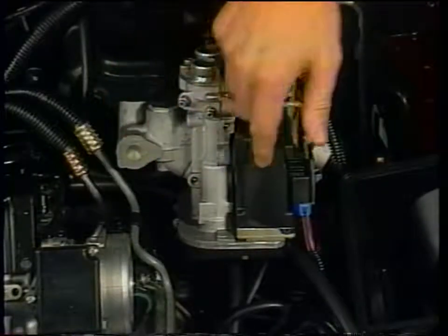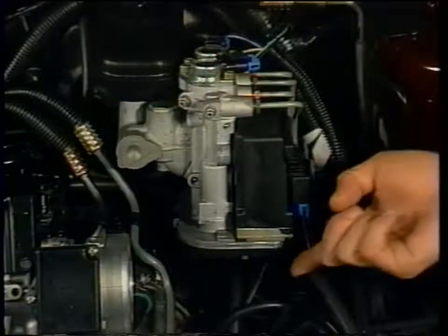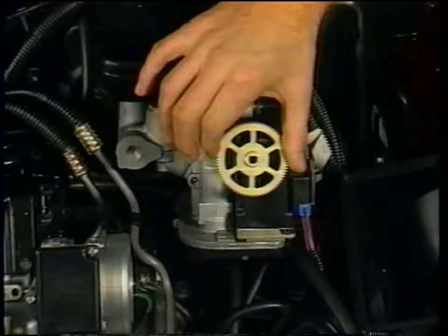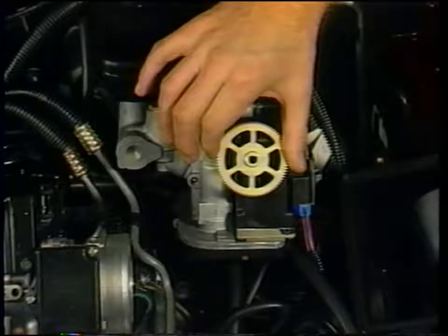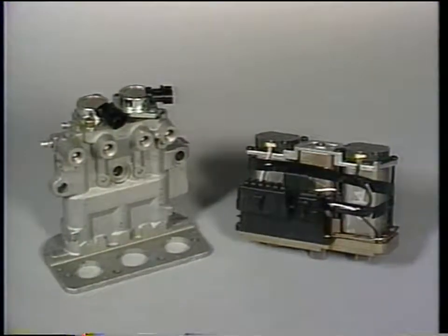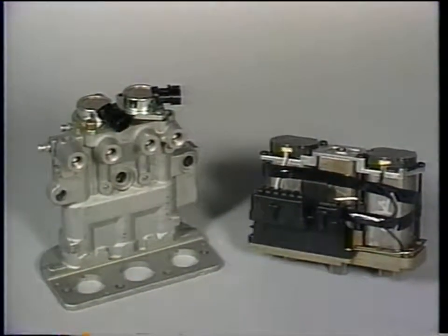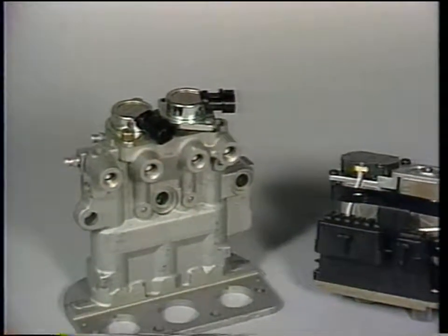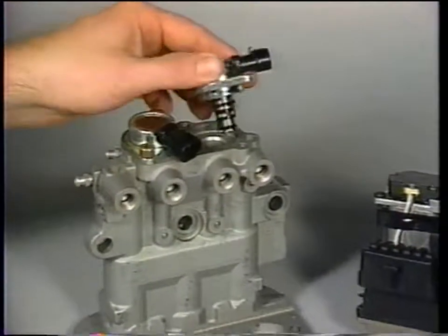The modulator, a motor pack, the isolation solenoid valves, the gear cover, and individual gears are all serviceable parts and can be replaced separately. The hydraulic modulator and motor pack assembly on the Delco 6 system is totally unique from the modulators used on other anti-lock brake systems.